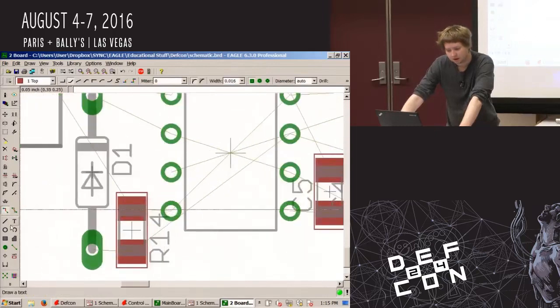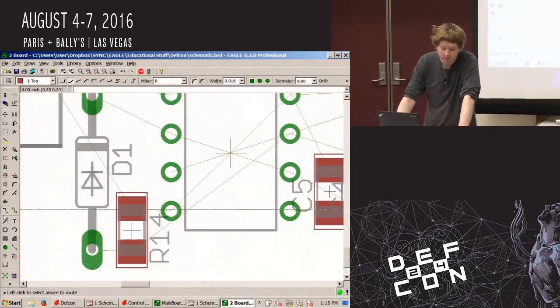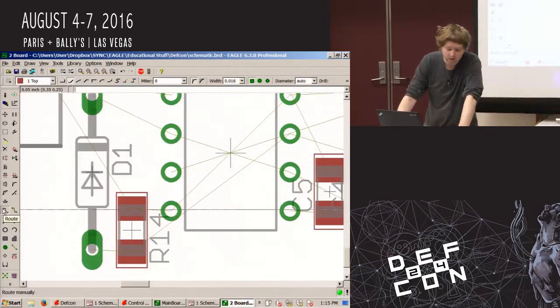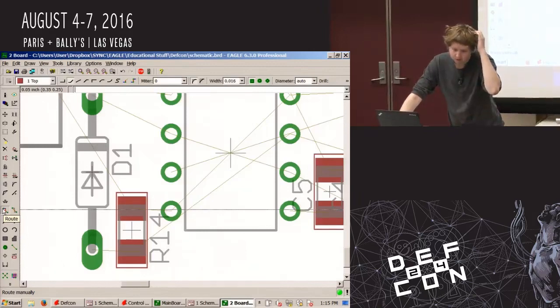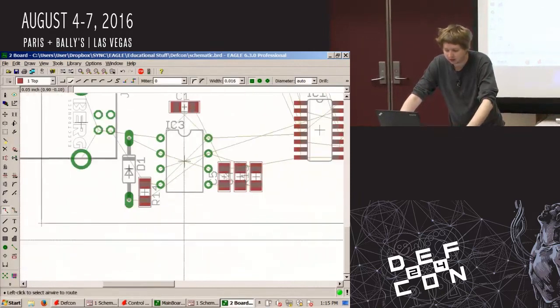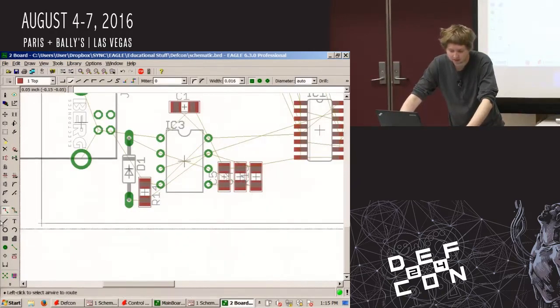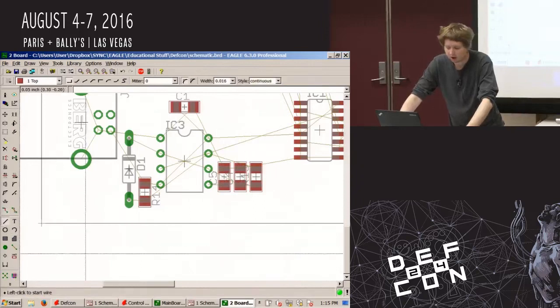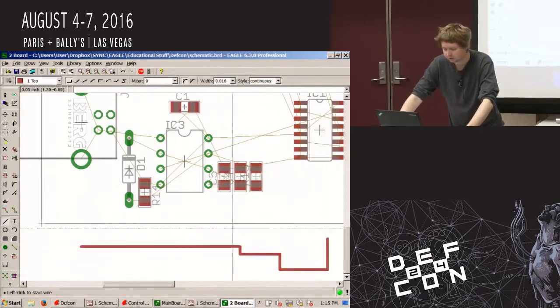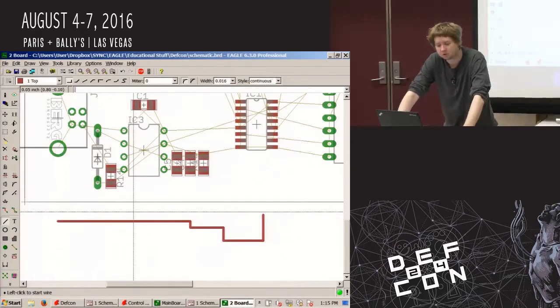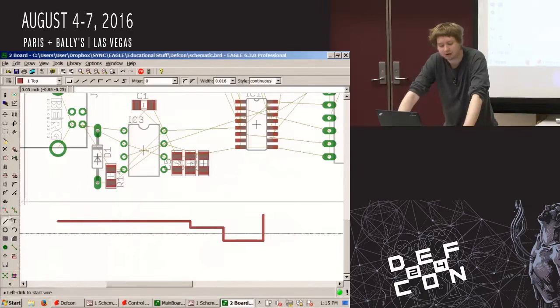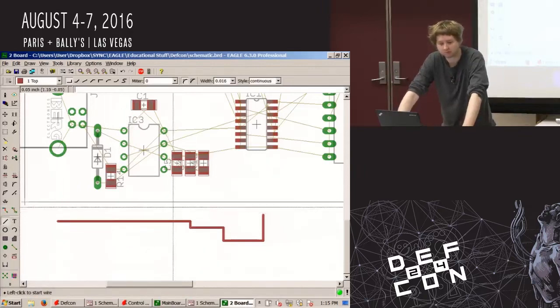So there are 2 trace buttons you can use. You can use this one here, the route to assign traces between pins. And this is the one I recommend doing 99% of the time, because this doesn't let you just make arbitrary traces. I can't click out here and start doing stuff. The one right below it, though, wire, you can create arbitrary traces. And sometimes useful, but so rarely that it's probably not even worthwhile you really knowing about that.